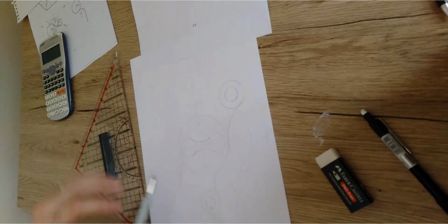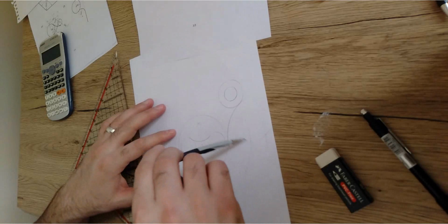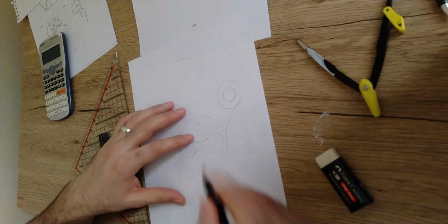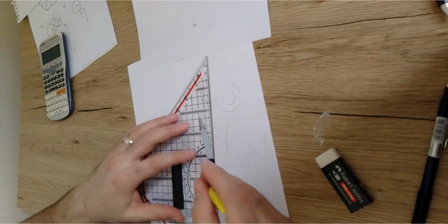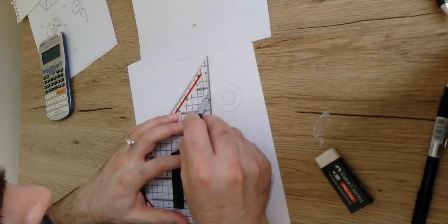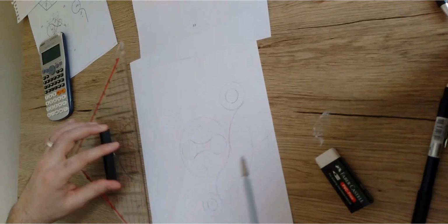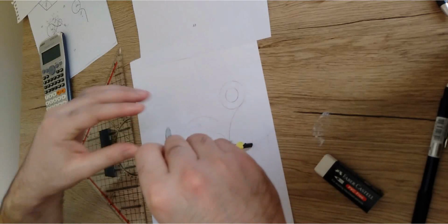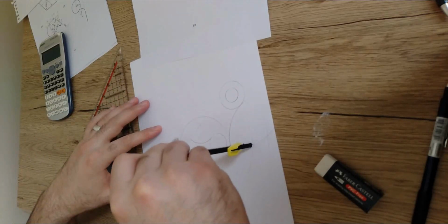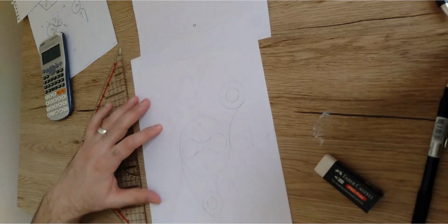Okay, then I'm just going to fix from the center of the small circle, and there is another curve here. So they are going to intersect together at a point. This should be the center point. Open the compass to 112. So it's going to be a little bit wider, 112. This is 110, 111, 112. Then from this center point, fix the tip here. Then you can directly draw the curve. If the measurements are accurate, you're going to get a perfect tangency, as I'm getting here. So it is perfectly tangent, as already shown.